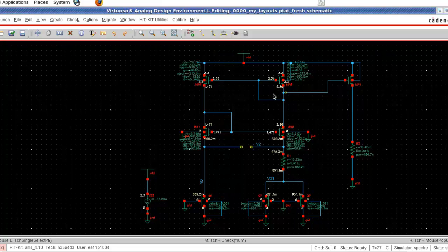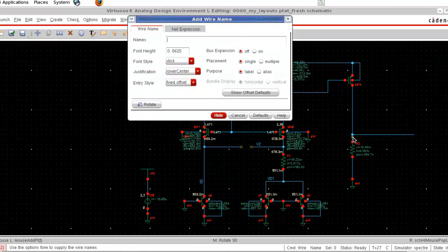So we said the current flowing through each branch is PTAT, and when we pass that PTAT current through a resistor, it will become a PTAT voltage. So we copied the current through to the third branch, and we passed that current through a resistor R2. R2 value we can change according to our wish. So now I am using the same value as R1 just to illustrate the PTAT structure, and the voltage across this is our final PTAT. So I'm labeling the node as PTAT.